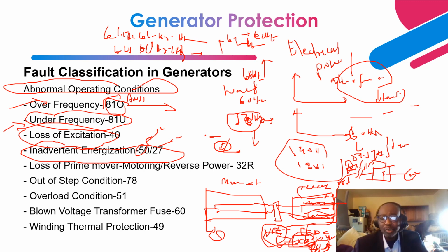So there's a turning gear motor that constantly rotates this turbine rotor shaft to prevent bowing, which can result in vibration problems. Let's say for whatever reason, due to operator inadvertent error, an operator should close this breaker. What happens? Then this turbine generator is going to operate as an induction motor and start drawing power from the network. So what this protection scheme does is protect the generator from inadvertent turning on of the breaker that can cause the turbine generator to act as a motor.